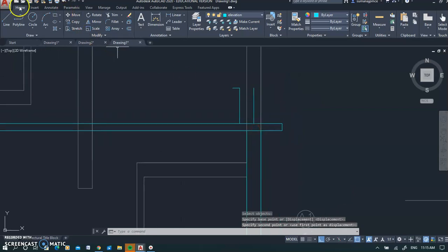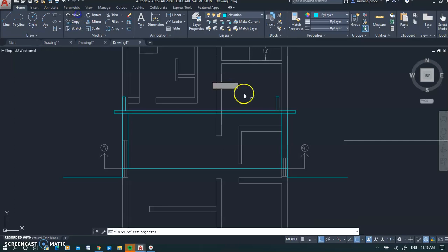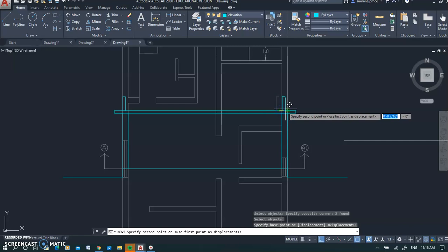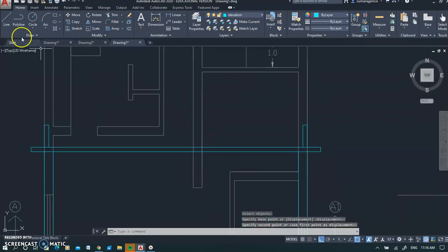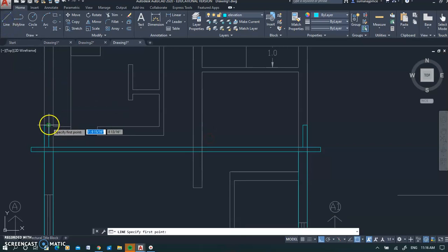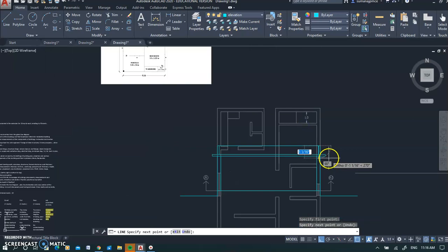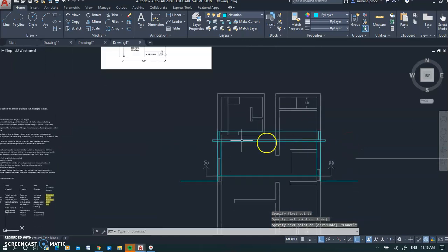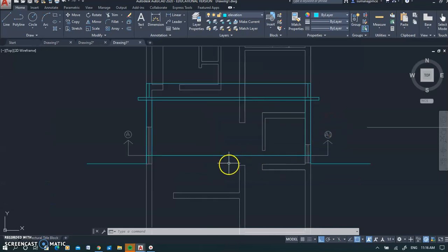Oh God, undo. I will move this parapet bit from here to here, zoom in and work, that's it. And if you see, you only see the back line of the parapet wall on the other side of the building. Because we have cut the building here, on the other side you can see it there. You just stand on the top of the roof and you can imagine how it looks. That's how the parapet is cut.